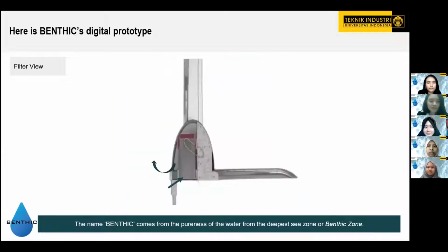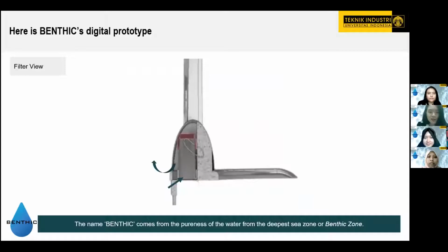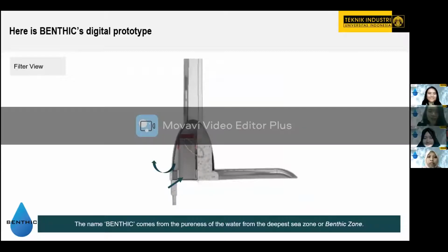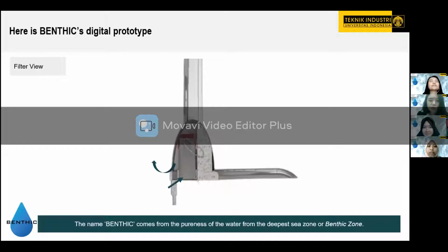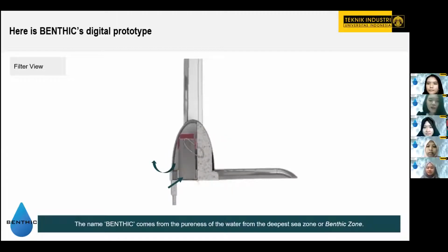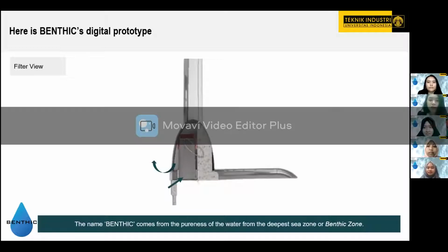The prism is the location for the built-in filter, which is easy to access through a lidded compartment. The mechanism to open the compartment is by unhooking and lifting the lid that is still attached by hinges. The built-in filter allows water to pass through 3 layers of filtration, which are an activated carbon filter to filter chemicals, ion exchange filtration to remove inorganic materials, and ultrafilter membranes to filter out pollutants, including viruses, resulting in the output of safe and clean, ready-to-drink water. The small tubular filter makes it easier for users to change the filter.